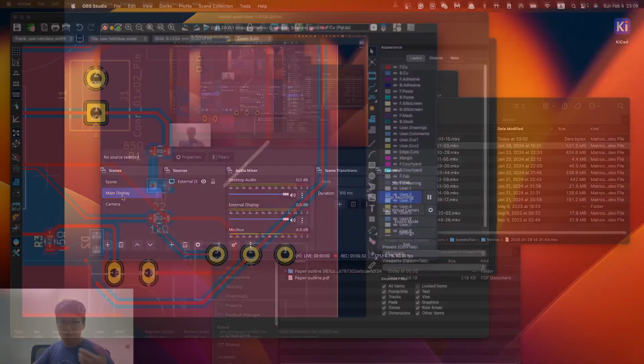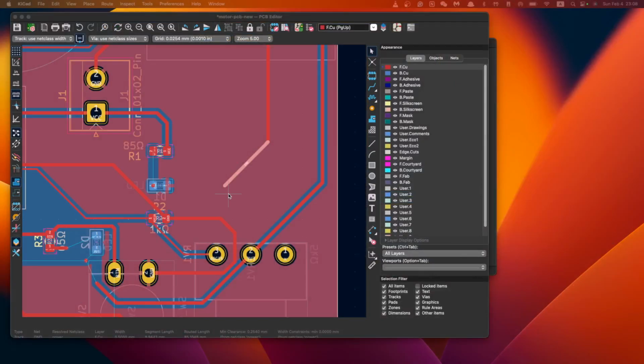For some simple one-sided PCB printing, those vias are always treated as holes or drills of your board, and of course with some copper connected, but those two coppers on each side of the board are not connected. But for real PCB fabrication, connecting them is easier. If you order it from a real PCB manufacturer and you are using a via, you don't need to connect those two sides of the via by yourself manually. They are already connected by the PCB manufacturer, which is pretty convenient for us.